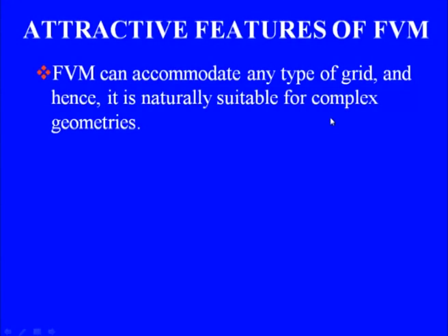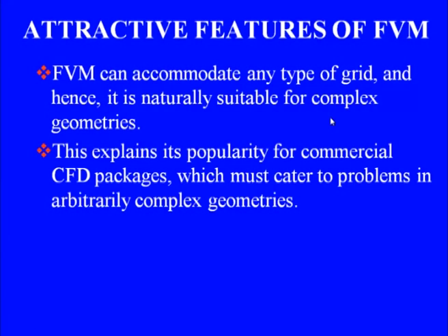Now, what we saw from the very beginning is that we can now have any type of decomposition of a problem domain. That is why the finite volume method can accommodate any type of grid, and hence it is naturally suited for complex geometries. And this explains its popularity for commercial CFD packages. You take any commercial CFD package like Fluent or Star-CCM or similar software, they are all based on finite volume formulations, because they must cater to the industrial problems which are defined in complex geometries.